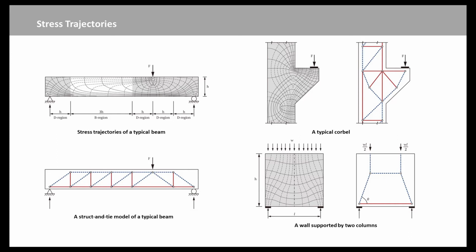The tensile forces in the ties have to be taken up by reinforcement bars. The reinforcement may be composed of several bars which are oriented according to the axis of the tie in the strut and tie model. In order to prevent surface cracking, additional reinforcement may be necessary, such as links and technological reinforcement.